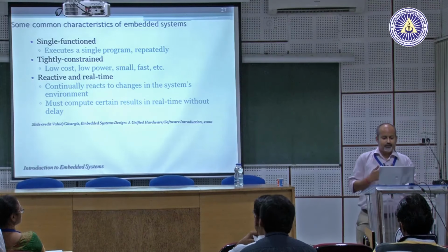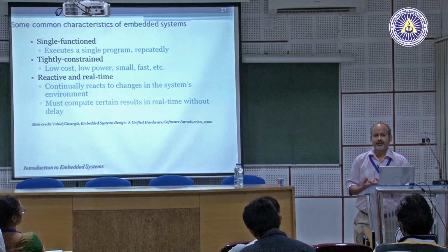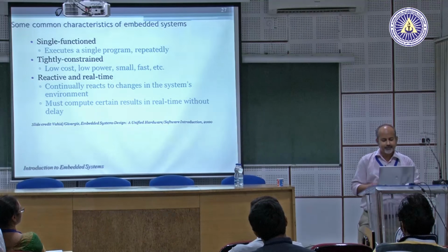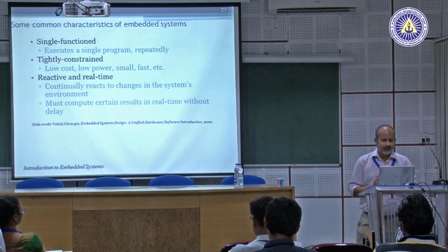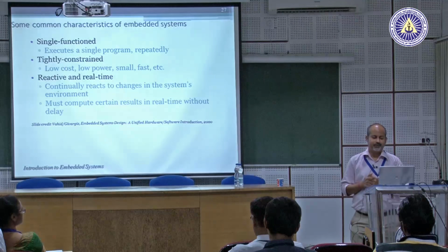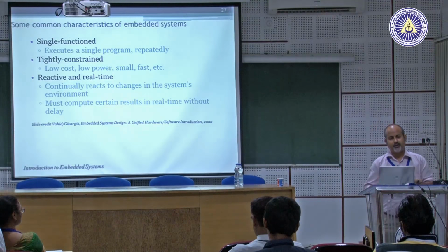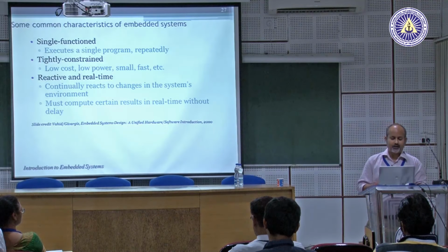But normally when you are running, it has to be running and reacting all the time, because it doesn't know when you are going to press the brake or when you are going to press the accelerator, and therefore it has to be reactive. And then many of the functions in embedded systems are real time, and by real time we mean that the response to an action that is caught by your sensor has to be time bounded, right?